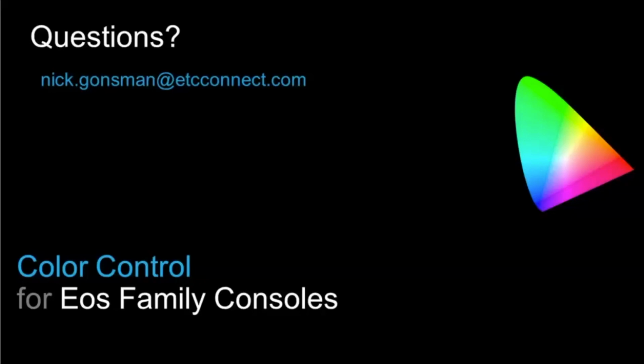In our own line, we run into that where color source has 2 branches. You have the color source original, which uses a blue emitter, the blue emitter that's in our 7 color system. And then you have the deep blue, which is an indigo emitter. And so the trouble there is if you patch a standard color source fixture and you hang a deep blue fixture, your color math is all off. And we make this stuff, right? So you've just got to be precise and give Eos a fighting chance to do its best, but it's always going to be limited by what gamut information we have and the accuracy of that fixture.